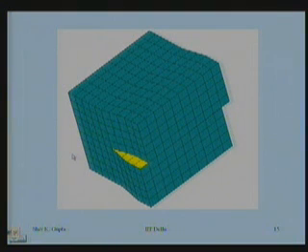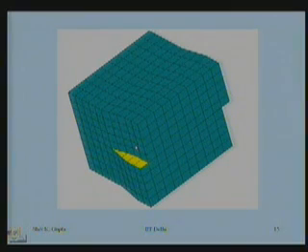As if you are going on these spiral stairs. You have seen these kinds of spiral stairs in IIT in a number of places. Go like this, going along the central line. So that is why it is called a screw dislocation. And like a clockwise or anti-clockwise motion of a screw, it is either going inside the crystal or going outside the crystal. That's why it is called a screw dislocation.